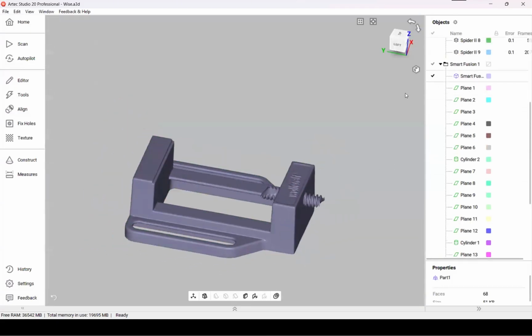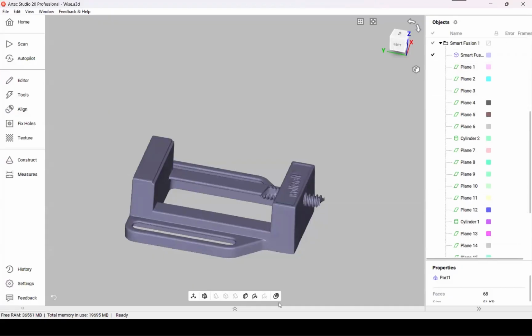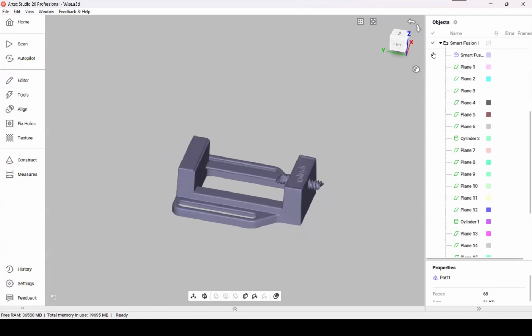And of course, initially the idea of this deviation check is to check the main features, like that all the slots correspond to the mesh, that all bores and other features correspond to the actual physical part.